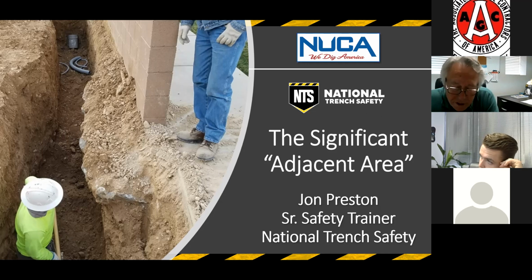The second limitation has to do with the soil. One of the concerns, and it's actually found in the definition of a cave-in, is that soil could come underneath a trench shield and entrap someone. That's why no one's allowed in a trench shield when it's being lifted, because the soil could come underneath the trench shield and entrap someone. So the two requirements to dig up to 2 feet below a trench shield are that the shield is rated for that entire depth, and secondly, that the soil will stand and is not going to come underneath that trench shield.